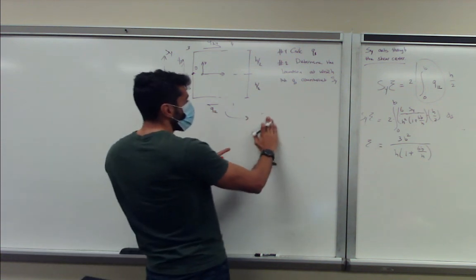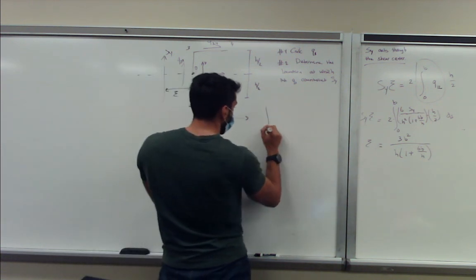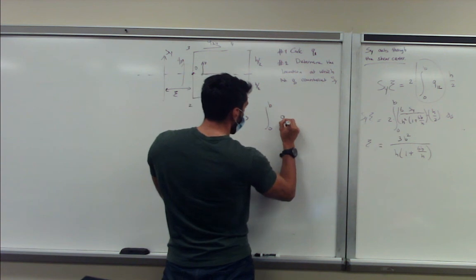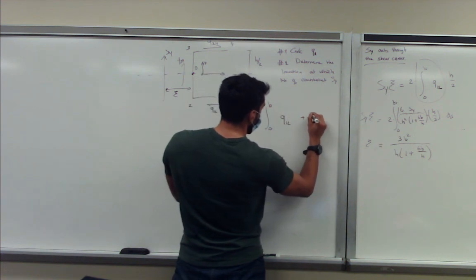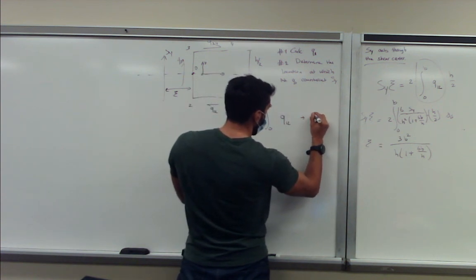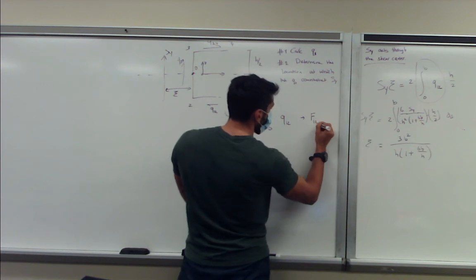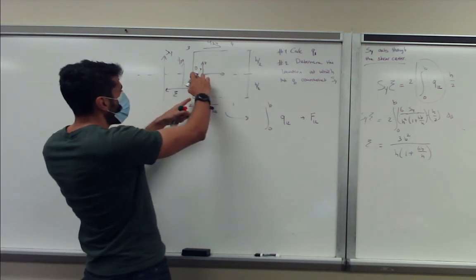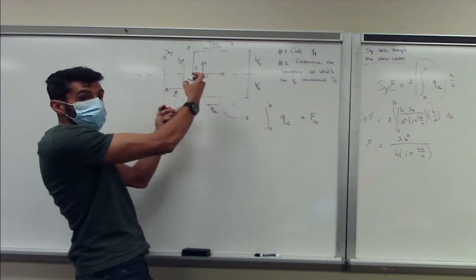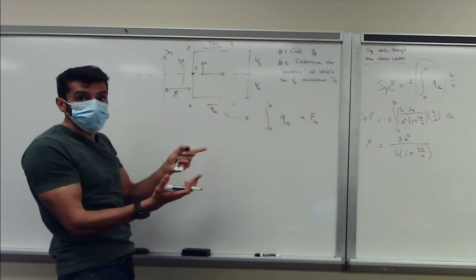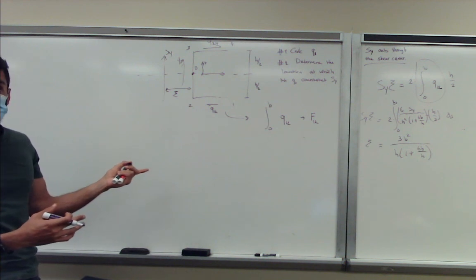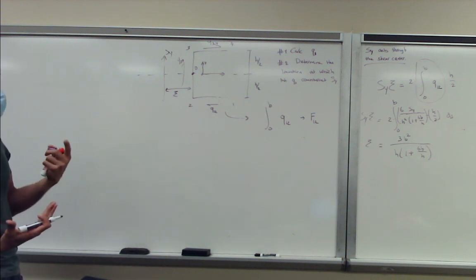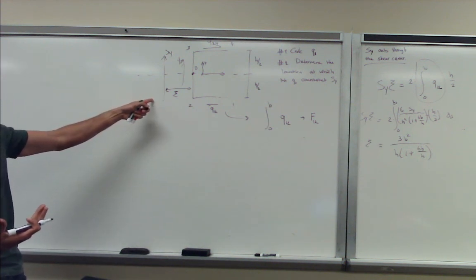So we have to take the integral from 0 to b of Q12 to get the shear force in 1, 2, right? And then we multiply that shear force by the moment arm around the point of interest, or the point that we picked. It can be any point. That gives the moment, and that moment must be equivalent to the moment applied by the external forces.